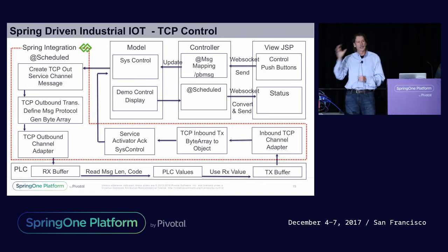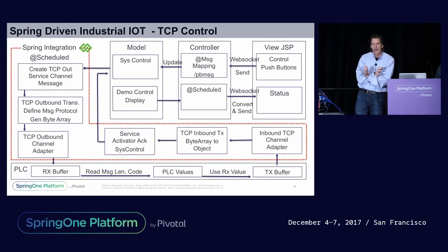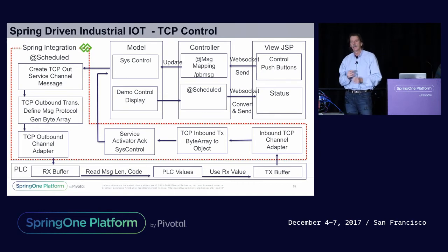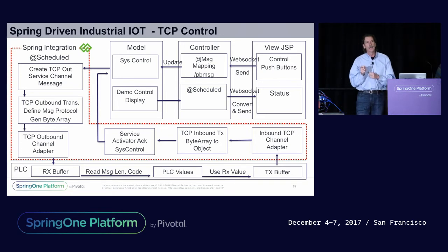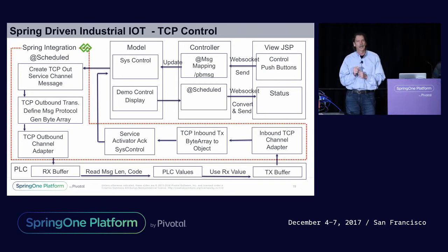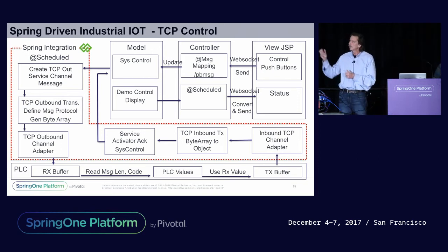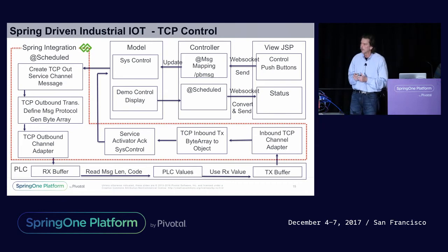We send those signals down from the IoT bridge to the low-level controller, and then the low-level controller turns around and sends them back to the IoT bridge. That is so that you can verify that they arrive, because in a control application like this, you have to verify that the signals arrived. And the other thing is that some signals are maintained, some signals are one-shot. This allows us to handle that appropriately based on the type of signal.